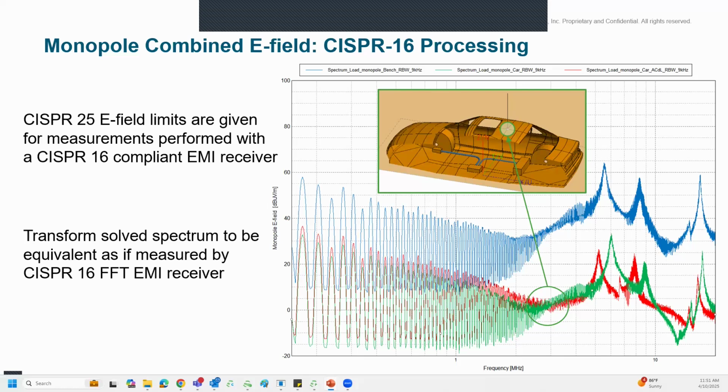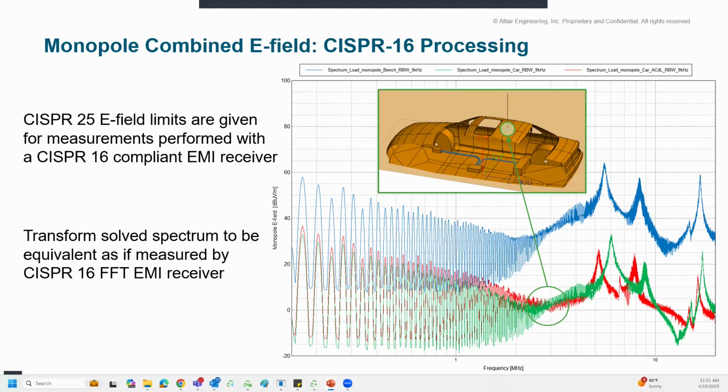Basically, we transformed and combined the load spectrum to a complex time signal. In POSTFEKO, it is possible to specify any desired time input once you do the simulations over a wide frequency range. Then we split the time signal into overlapping partitions and apply a Gaussian window function to each partition. Then we do an FFT on all the windowed partitions. For the peak detector, we take the maximum spectral response over the partitions. For the RMS detector, we calculate the RMS spectral response value over the partitions and then store the peak and RMS frequency responses.